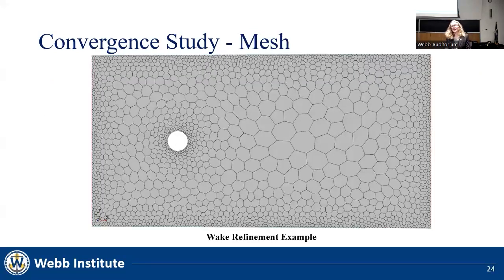Part of the CFD setup includes creating a mesh. To create the mesh, the geometry is broken into finite pieces called cells. Each cell takes inlet conditions and solves the Navier-Stokes equations to find outlet conditions. At each time step, every cell in the entire mesh does this. The cells then pass their outlet conditions to the next adjacent cell in the mesh to use as the inlet conditions for that cell. This is repeated for each time step in the simulation.